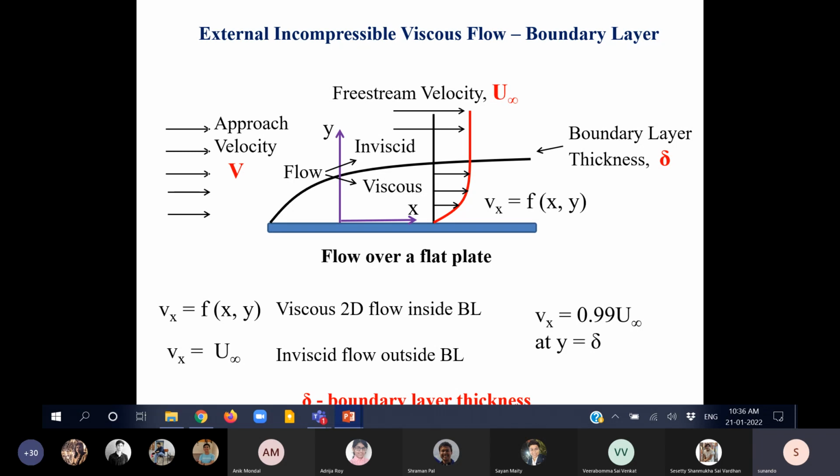This concept is probably one of the most interesting in chemical engineering as well as in mechanical and aerospace engineering. It is the concept of boundary layer. We have had some discussion on the boundary layer before, and I'm sure you had the same discussion for heat transfer as well. So we understand that everything happens in a very thin layer close to the interface between a solid and a fluid.